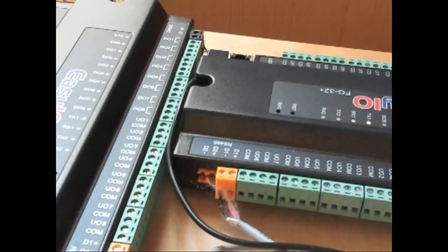What you can see here are two FG32 Plus controllers. One of them is acting as a BACnet client, which is managing the other one that is acting as a BACnet server over BACnet MSTP serial connection. Now, see the two lights flashing? You can certainly see it on the right-hand controller, and you may see it on the left one, but they are both flashing, and that means we have a good electrical connection between the two. This is very important when you're adding any BACnet devices to make sure the electrical connection is correct. If these two lights are not flashing, the FG client will not discover the MSTP server devices. So please check the baud rates, make sure the connections are correct, and get those two lights flashing beforehand.